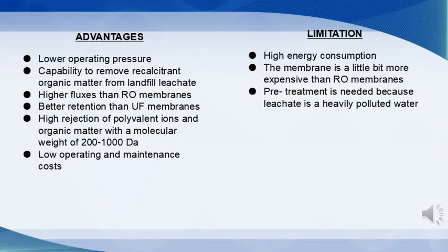There are a few advantages and limitations when using nanofiltration membrane. The first advantage is it requires lower operating pressure. The second one is it has the capability to remove recalcitrant organic matter from landfill leachate. The third one, it has higher flux than RO membrane. The fourth one is it has better retention than ultrafiltration membrane. The fifth one is